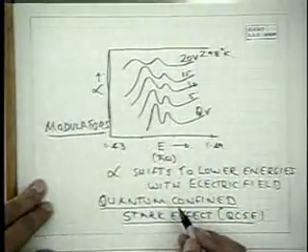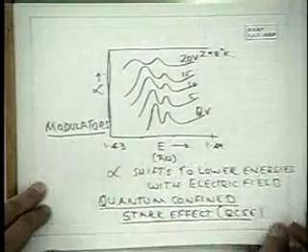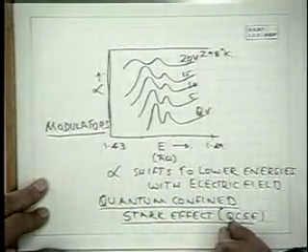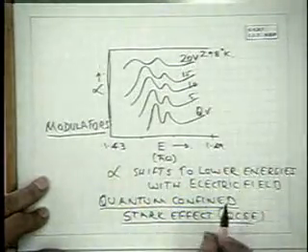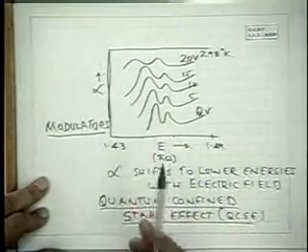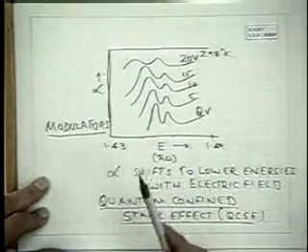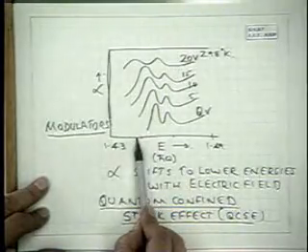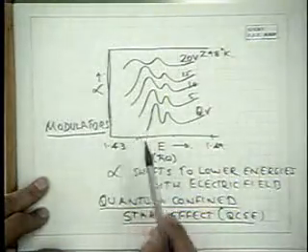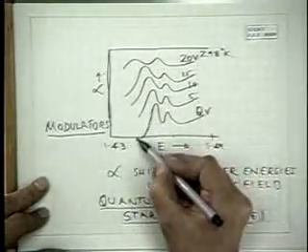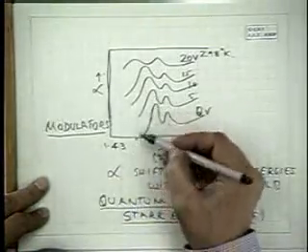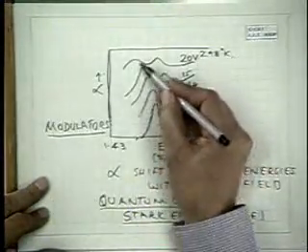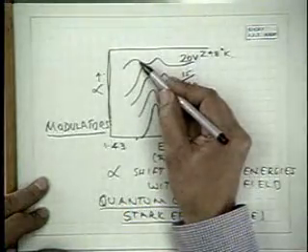This is a very fast effect because there are no carrier injections involved. It is just an electric field effect. Suppose you have a light source operating at this wavelength. So the optical absorption is very low. Without any electric field, light is transmitted. But if you apply the electric field, optical absorption becomes large and the light is cut off.